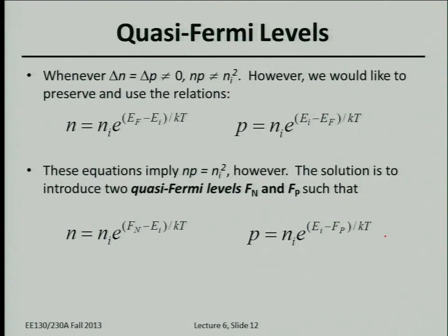Okay, so a couple of minor topics before we can start talking about semiconductor devices. It's the concept of a quasi-Fermi level. So remember, what was the purpose of a Fermi level, or keeping track of the Fermi level again? Can you remind me? Average energy of an electron. That's true. But in a semiconductor, the Fermi level is in the band gap, so that's where no electrons can exist.